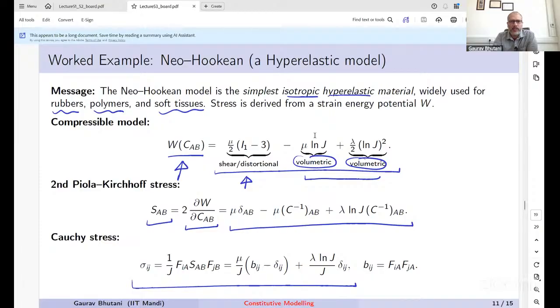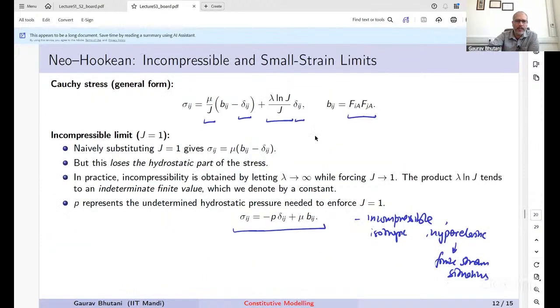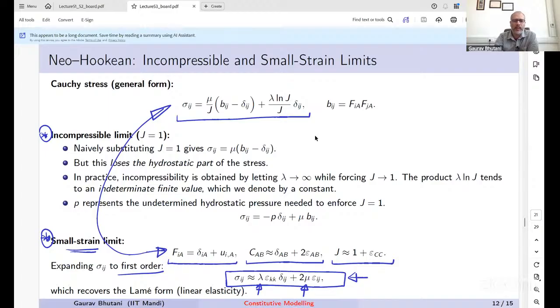We already had assumed the material to be isotropic, but it was hyperelastic, so it was a finite situation. Now, if that's a more general case, right? And if I take the approximation of infinitesimal strain situation, that should give me the constitutive model for infinitesimal isotropic elastic solids. It's all elastic we're talking about. And that is exactly what we have in terms of the two Lamé constants, lambda and mu, in the last expression in this slide.